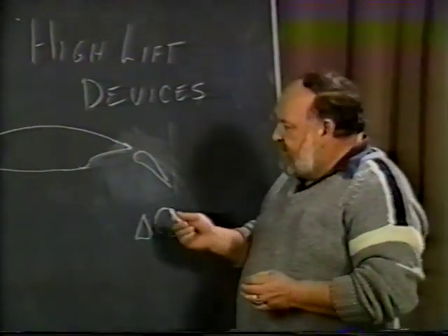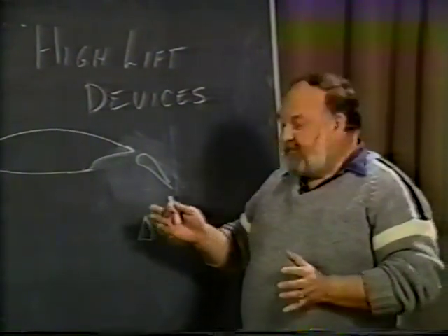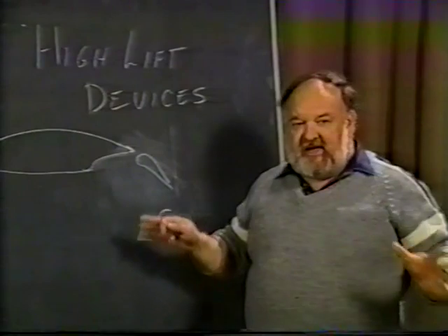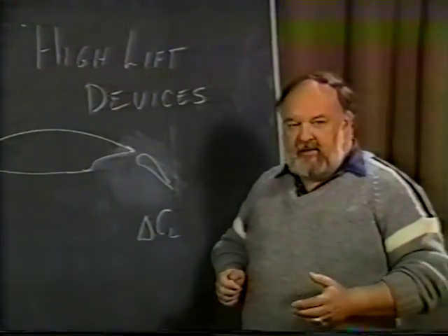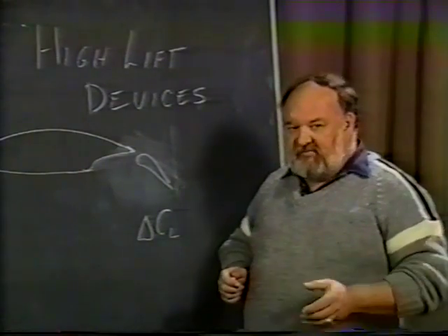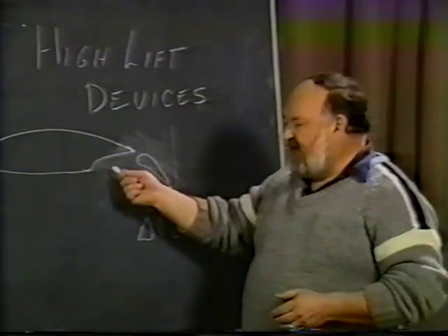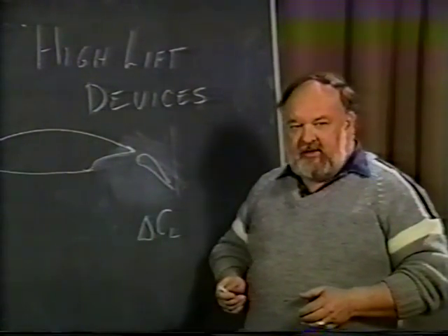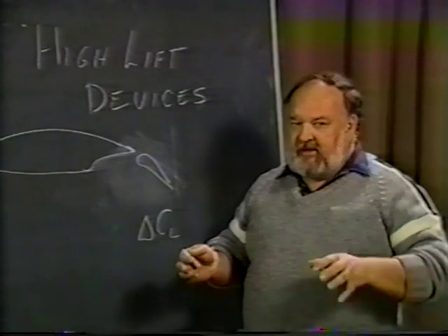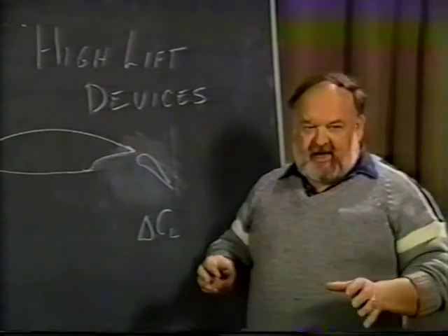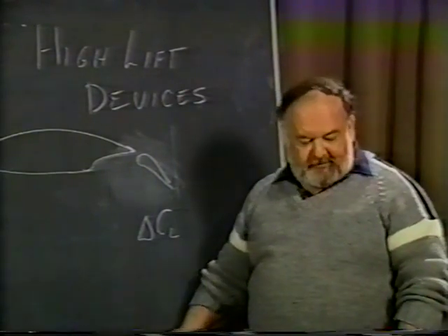So these two flaps, the single slotted flap and the Fowler flap, are essentially the same, but the advantage of the Fowler flap is that you actually have more area exposed. A Lockheed Connie, P-38, a lot of Lockheed's airplanes use the Fowler flap. The disadvantage is that you probably have to have a track assembly to activate this flap, and that's much more difficult to make. It involves rollers and cams and other assemblies, which can present maintenance problems.